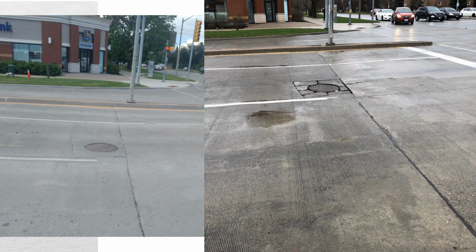But the unfortunate part about this one is that it's directly in the wheel path, and right where vehicles are stopping. You can see the stop bar here. This is for eastbound traffic on Bailey Street. So over time, vehicles would stop and start, and they're right on this maintenance hole. And this is what the maintenance hole looks like today. It just got pounded by traffic, and it's right at an isolation joint as well, along the side of it. So this has broken up over time. This has now been, I guess, 3 years or so.